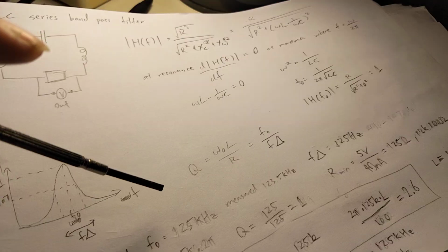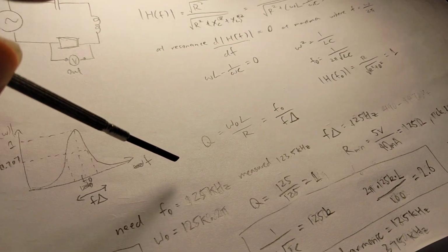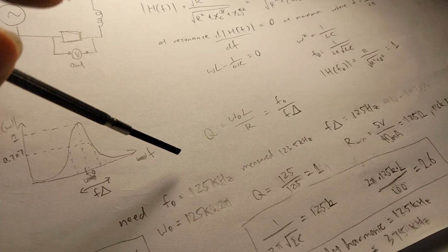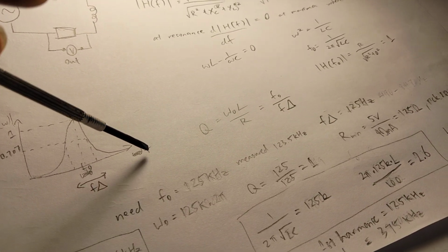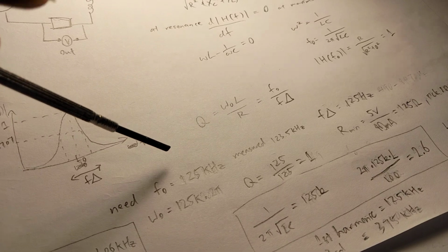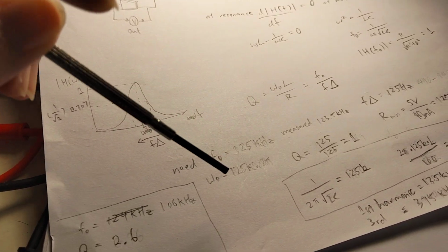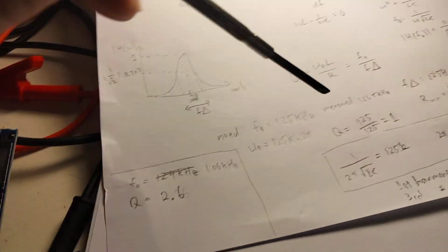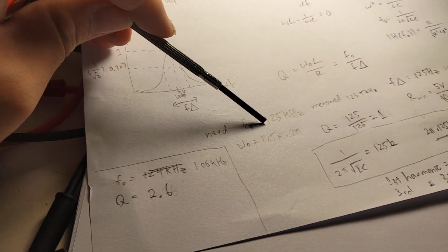But it turns out that I don't have the capacitors and inductors necessary to filter that. Filtering 980 hertz requires quite large inductors and capacitors, so I just don't have that. So I had to actually overclock my Arduino in order to generate a PWM signal of a decent frequency.